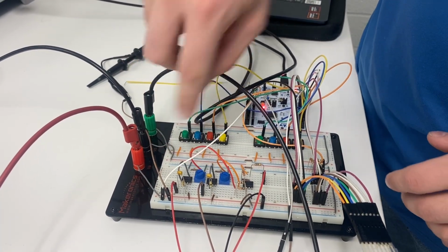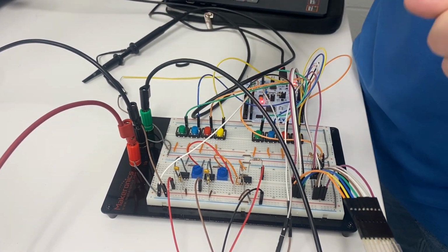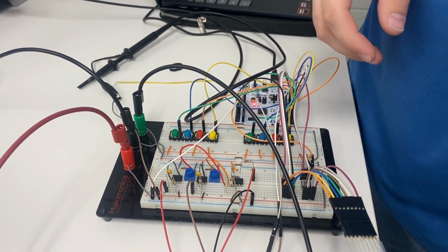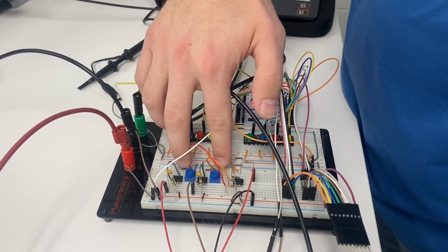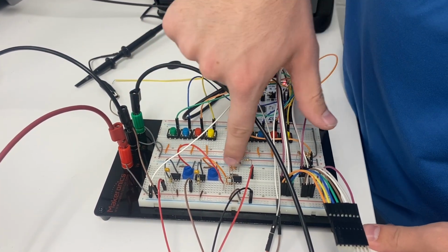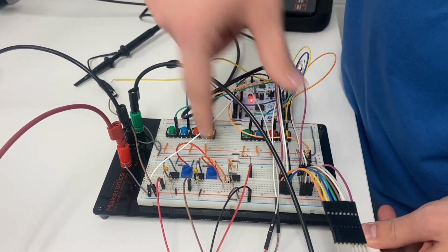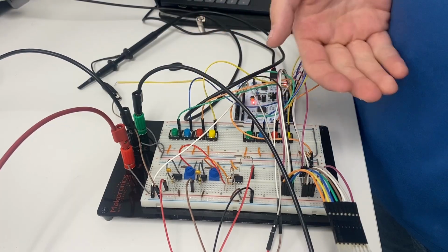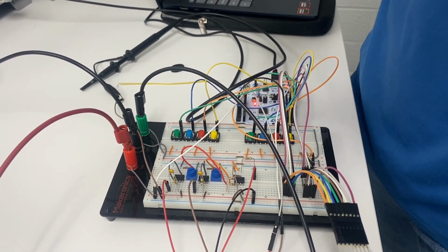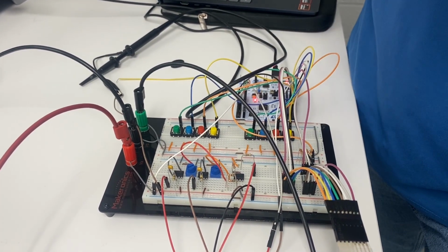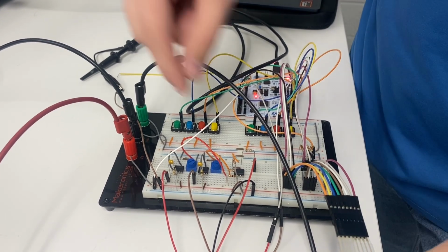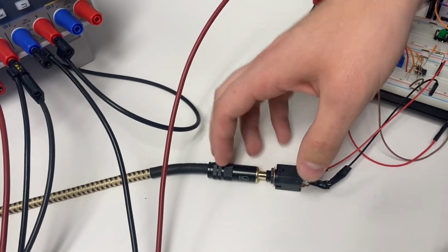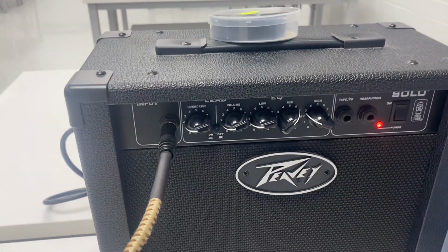It is then run into potentiometers to control the volume, so we can quiet our recording or quiet the notes that we're playing. And those outputs are then run into another op amp serving as a summing amplifier to combine them into one single output. This op amp also scales down the voltage to a level that a guitar amp would expect so that we can use that voltage safely. It is then run into a simple 1/4 inch jack and my guitar amp where we're able to hear the sound.